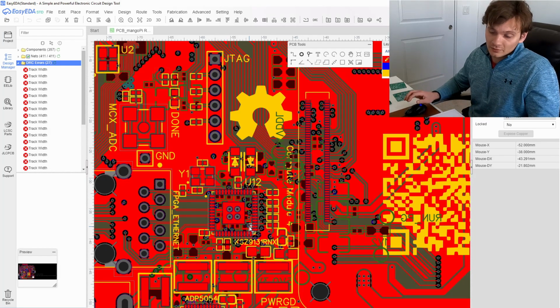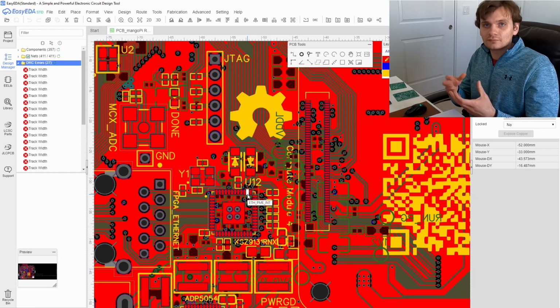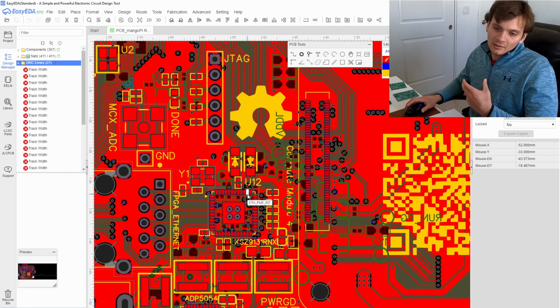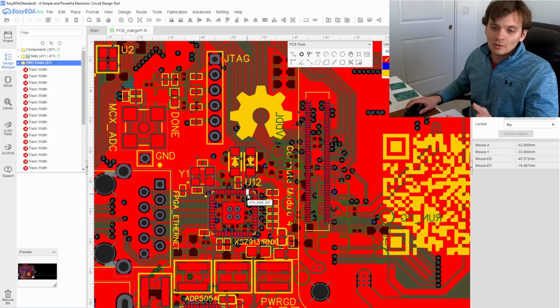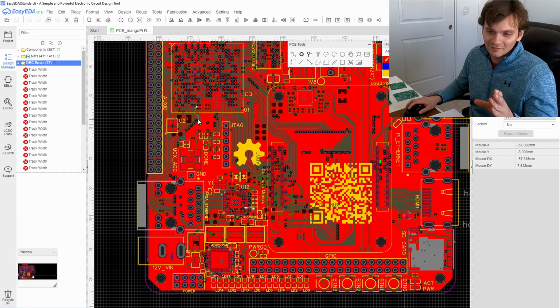From there, it can get even worse because integrated circuits are complex and their pinouts are not going to be the same, and they might even have slightly different functionality, or maybe a replacement Ethernet PHY chip needs to have an extra 3 GPIO signals. And you can just see how that turns into a ton of work.